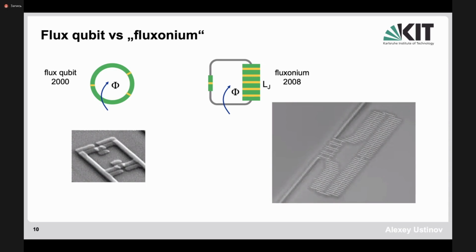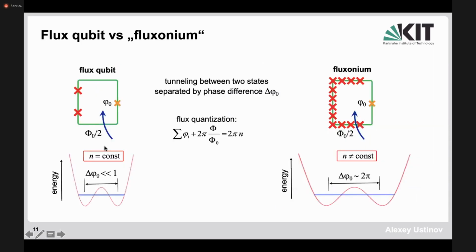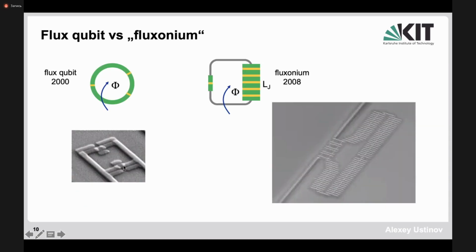More generally, the picture which you see here is the flux qubit, which has 1, 2, and 3 junctions. And on the right, you see the geometry of the Fluxonium, which has a more complicated, tree-type structure. The junctions are actually these long bars where you have the overlap between the 2 electrodes, and the connection here is a quite small, narrow wire.